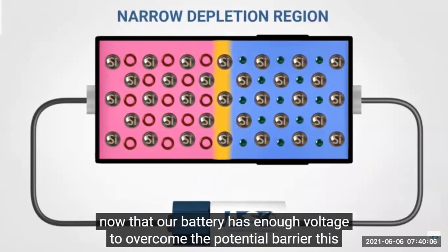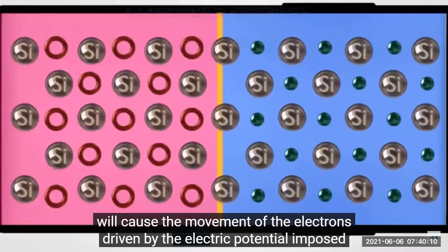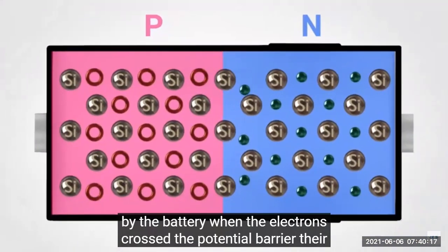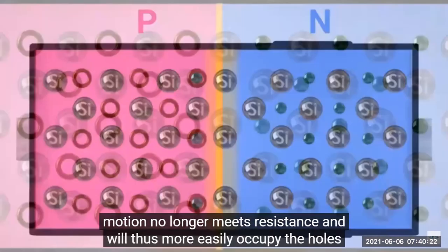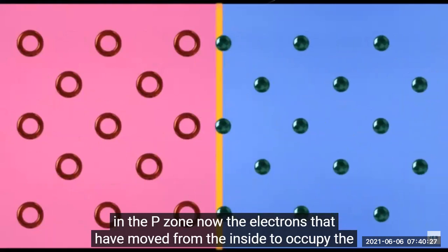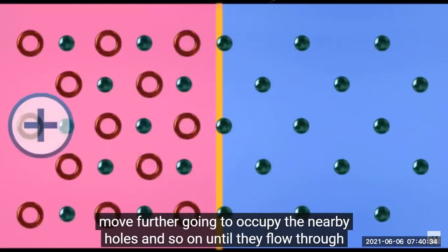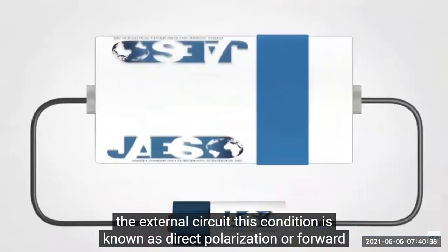Supposing now that our battery has enough voltage to overcome the potential barrier, this will cause the movement of the electrons driven by the electric potential imposed by the battery. When the electrons cross the potential barrier, their motion no longer meets resistance and will thus more easily occupy the holes in the P zone. Now, the electrons that have moved from the N side to occupy the P side holes, due to the attraction of the positive pole of the battery, will move further going to occupy the nearby holes and so on, until they flow through the external circuit.